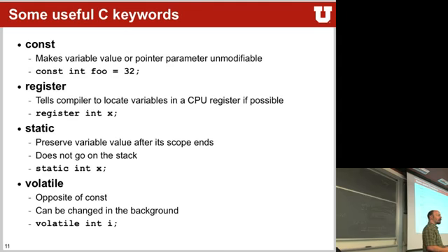There are a couple of things that you usually use in embedded systems that you don't always see in regular C code. We have the modifier const. It makes a variable constant, so you can't modify it, and hopefully your compiler would tell you that this is a non-modifiable variable that you just tried to modify.